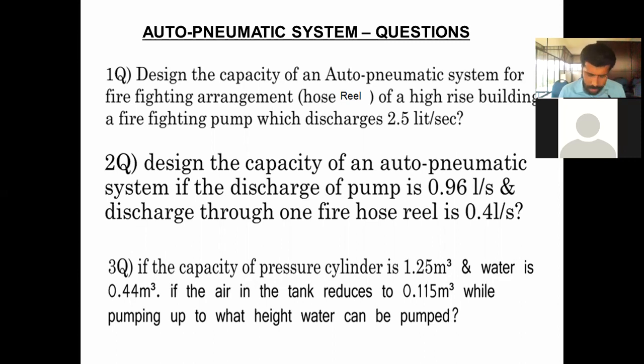So I will explain what that is. It is the jockey pump. It is designed to keep the pressure in the system elevated to a specific level when the system is not in use, so that the fire pump doesn't have to run all the time and the system doesn't go off randomly. Since pipes leak over time, the water pressure inside them automatically goes down. The jockey pump senses this and fills them back to the normal pressure. Secondly, this pump prevents the sprinkler system from being damaged. So that is the use of jockey pumps.